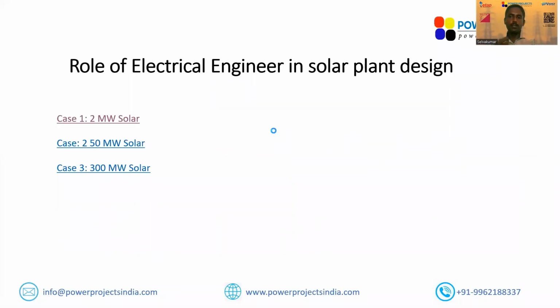Like, it means to say what are the points which can be optimized. For example, if you're optimizing the on-load tap changer range for a solar plant, that's a massive task. If you're optimizing the transformer impedance and the short circuit rating of the switchgears and RMUs, that's another important aspect. If you're optimizing the reactive power compensation rating, that's another great thing. So the role of electrical engineers at the design or engineering stage is something great, where you